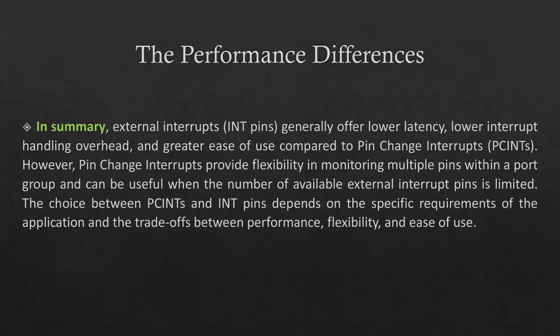In this project, we are indeed using both hardware external interrupts and software external interrupts via pin change interrupts, PCINTs. In the examples I'll show you, we'll use built-in Arduino IDE functions. With each button press, it's intended that a variable of type integer increases by 1 unit, and its value is displayed in the serial monitor.